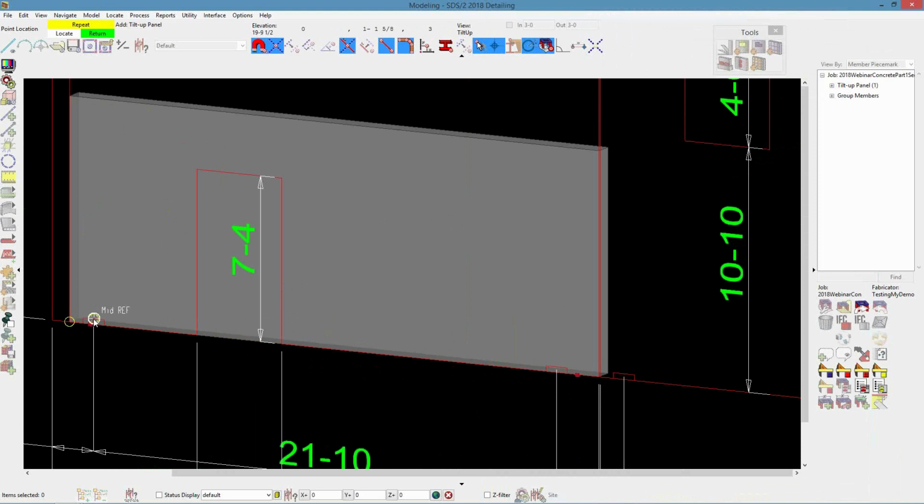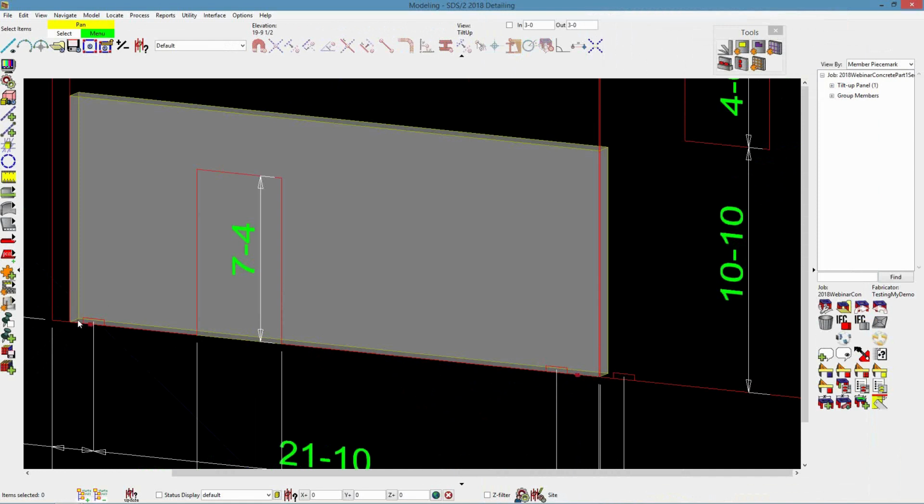Hold that in your left hand, and then you have your interior part of the wall and your exterior part of the wall. Now, if I go from right to left or in a plan view from top to bottom, if I pick interior as my reference, what that means is you'll have the whole wall on the interior side or on the inside of the lines that you have picked.